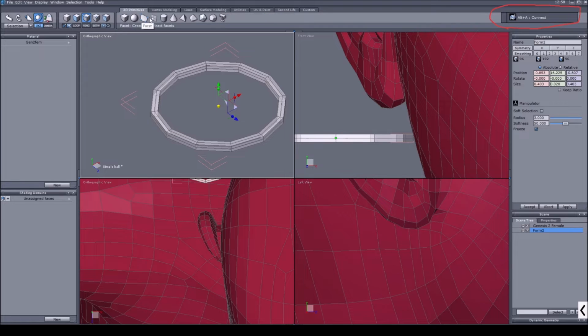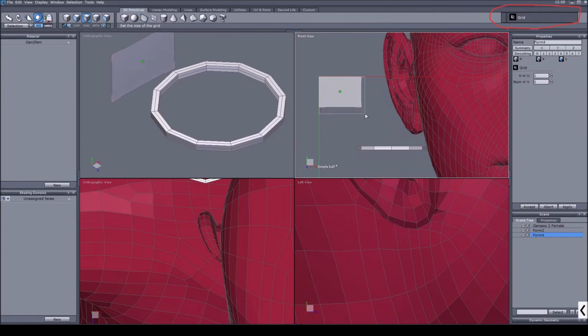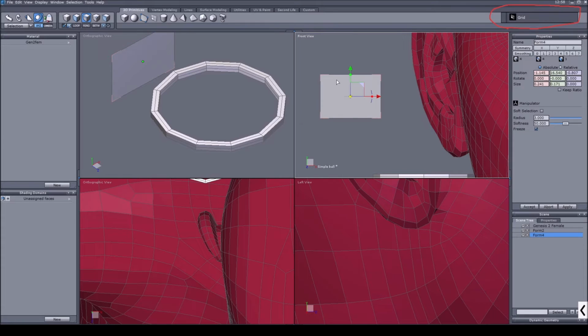planes. So basically, to show you what we just did, on this grid, I have a flat surface, and I have a few different options. So for example, if I go to Tesselate, I can cut this up into different shapes. I can cut from top to bottom and from left to right. I can cut from each corner to the other corner. So I can subdivide this in different ways. But I don't have the option to actually cut this up only lengthwise or only horizontal or only vertical if I want to. With Tesselate at least.